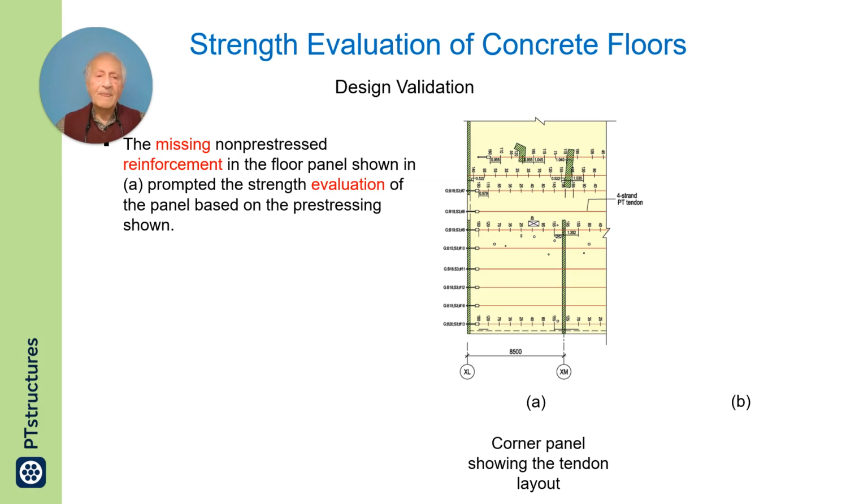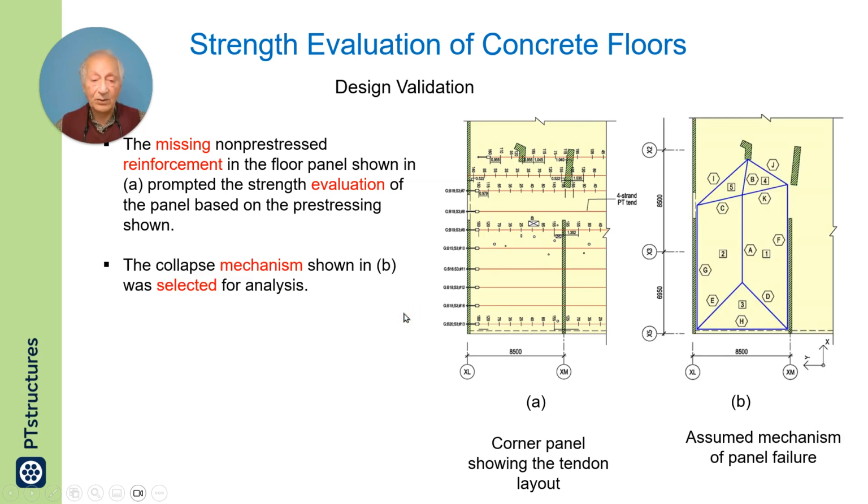Now I want to go through a number of design examples. The image shown at the right is a case we had to evaluate. The post-tensioning is shown left to right, but after construction it was determined that rebar was not placed as shown on plan. So we had to calculate the capacity of this region based on the post-tensioning alone.